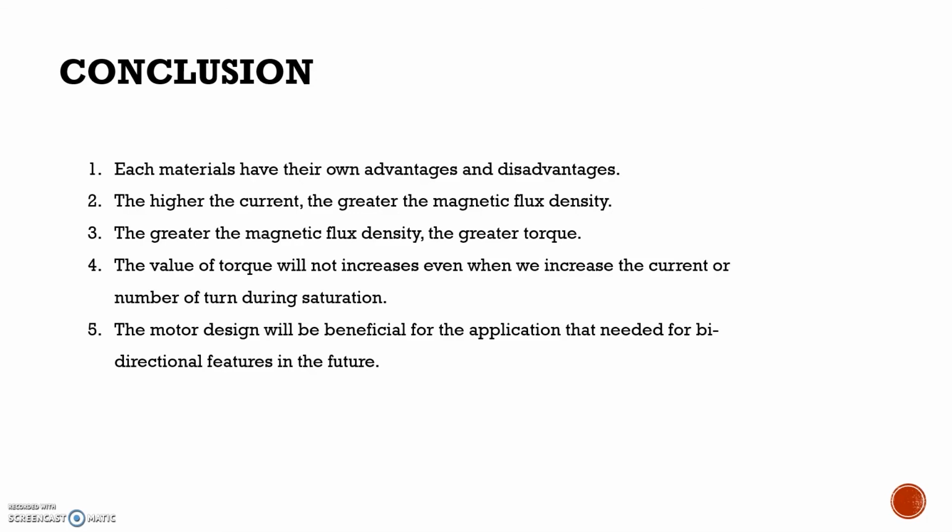The higher the current, the higher the torque, and the greater the magnetic flux density. The greater the magnetic flux density, the greater the torque. The value of torque will not increase even when we increase the current or the number of turns during the saturation level. And the motor design will be beneficial for applications that need bi-directional features in the future.